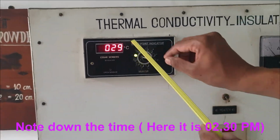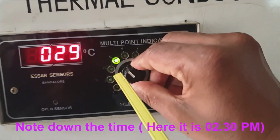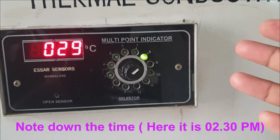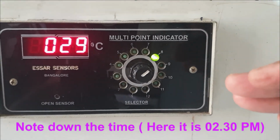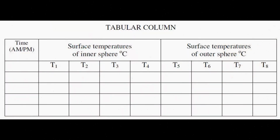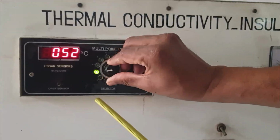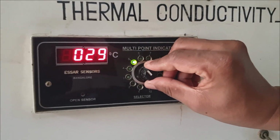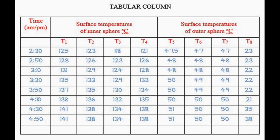Now for doing the experiment, we need to note the temperatures at each of these points at different intervals of time. We put the time in the left column and all the temperatures in the other columns, and we will find that with time there will not be much change. That is the point where it has reached steady state, and we take these temperatures and apply them in the equation to find out the thermal conductivity.